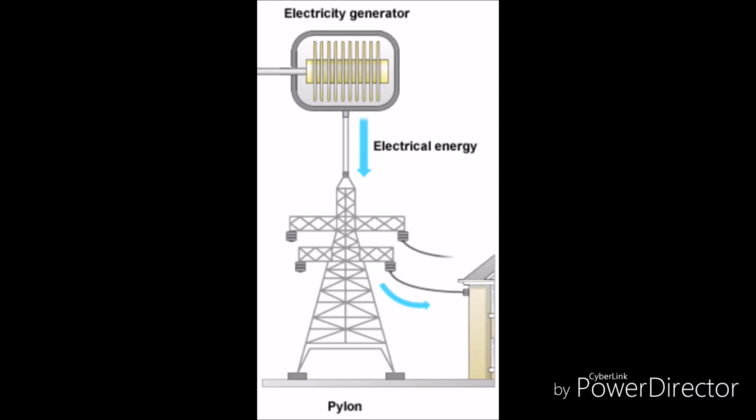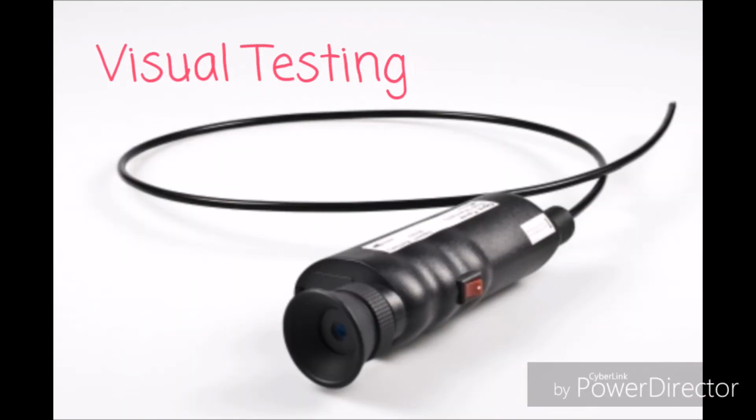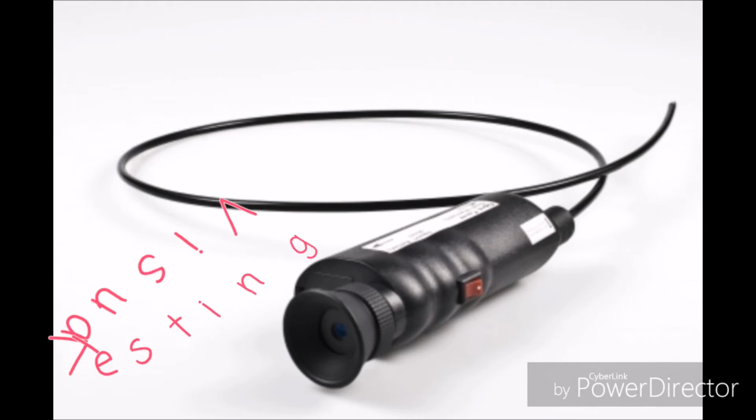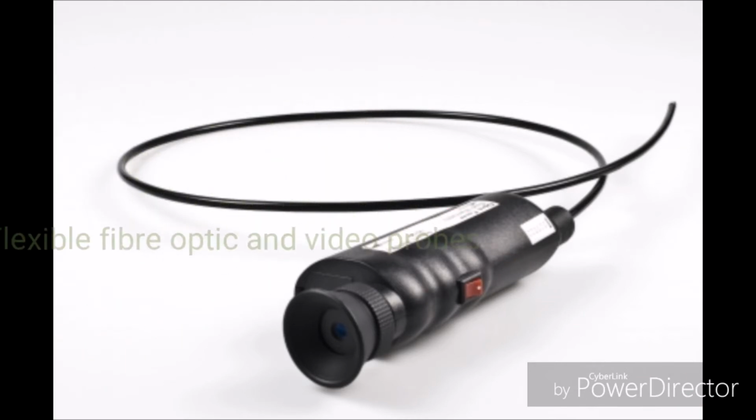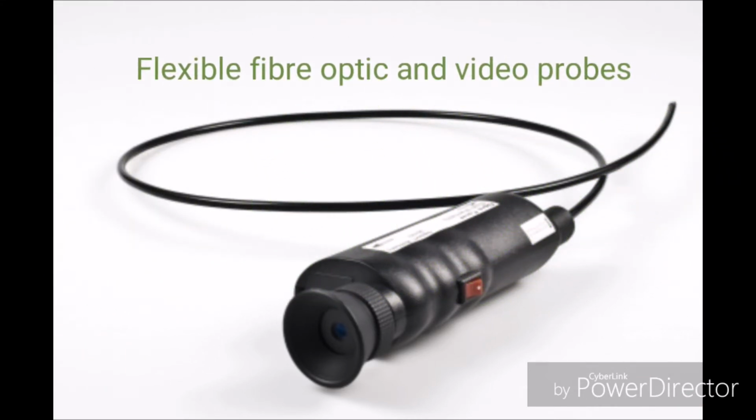NDT application for generator, first is visual testing. Flexible fiber optic and video probes are used to inspect generator areas through access ports with limited access.